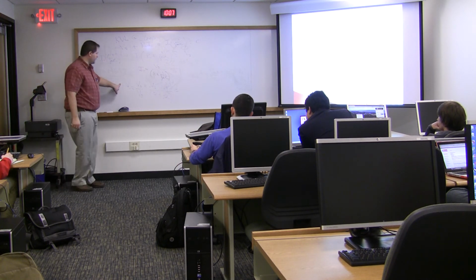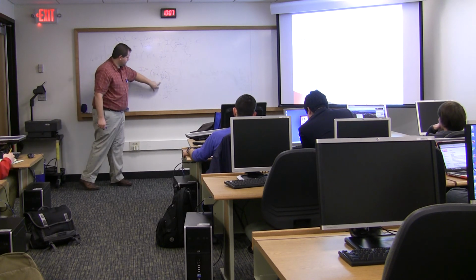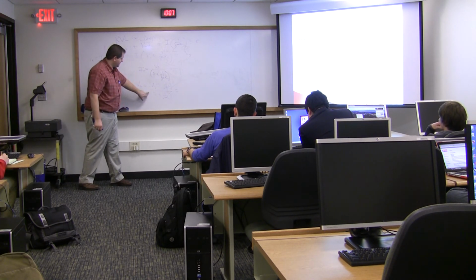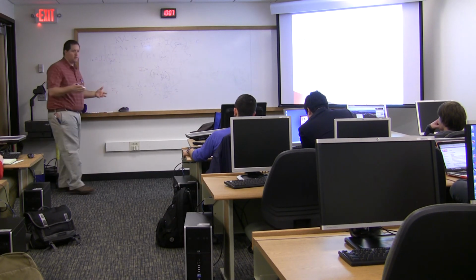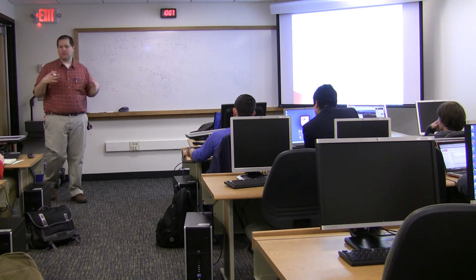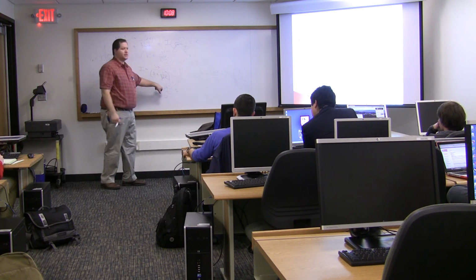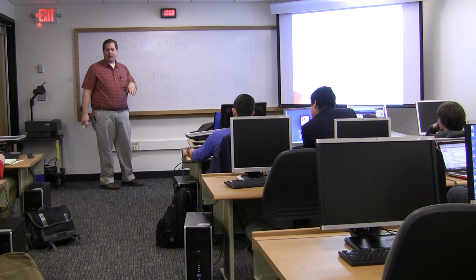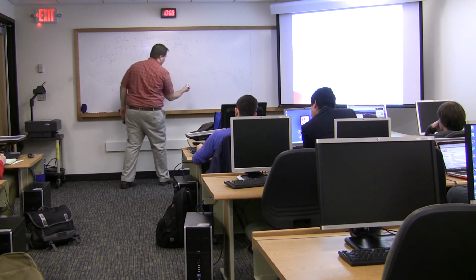So my transfer function, which is the output voltage over the input voltage, is this 1 over j omega C divided by R plus 1 over j omega C. Now, I can clean that up, right? I can do the algebra to get that into a little bit nicer form, which I really ought to do, especially because we don't like j's in the denominator, right? They are ugly. No one really likes that.